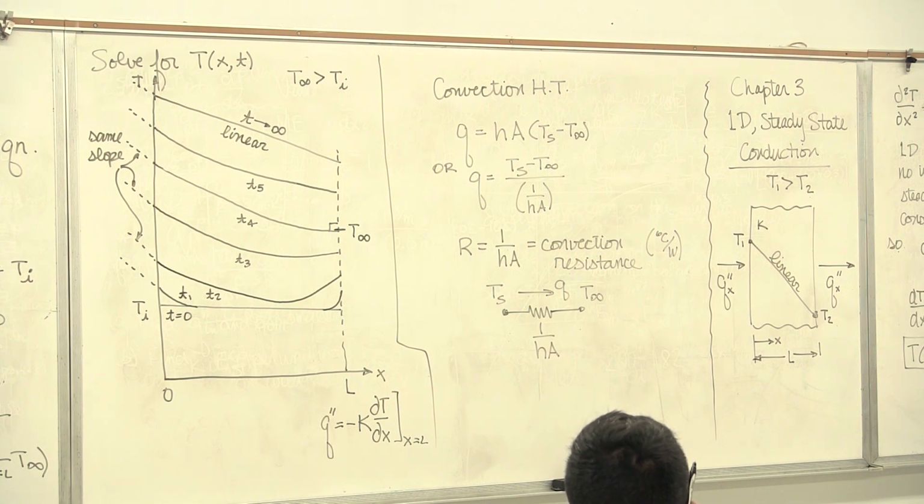The area of the wall: the bigger the area, the smaller the resistance, and the more heat flows. Makes sense, the bigger the wall, the more heat flows out of the wall. So these three parameters in the resistance itself do make common sense.